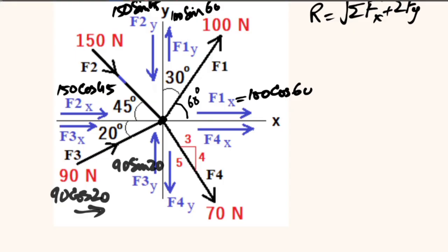Now another thing is to find the angle. Angle is not directly given here, it is given in the form of this triangle 3, 4, 5. So the ratio of the sides is given. So from this we can easily calculate this angle theta, which is the same as this angle because these two are parallel sides. So from this triangle we can easily calculate the values of sine theta and cos theta. If this is 3, this is 4, this is 5, and here you have theta.